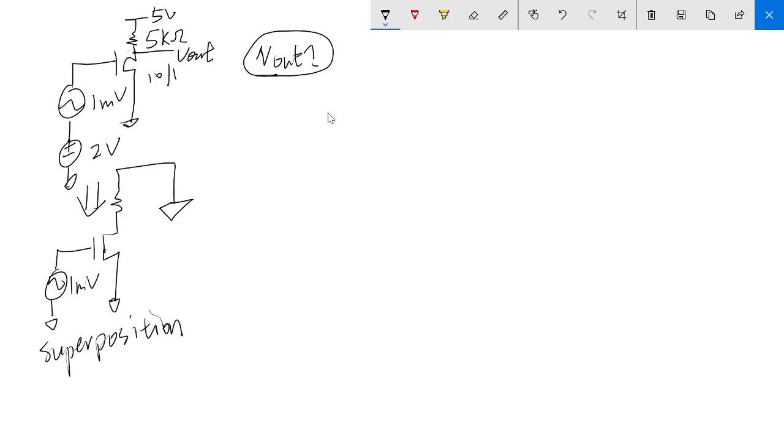So it's the same concept. I just ground all these DC signals. I know the DC signals are not ground, but compared to the AC, they are being treated as an AC ground. This is a pretty interesting concept, and it's kind of virtual. You couldn't imagine why, but just try to use this for AC analysis. This is really, really helpful and handy.